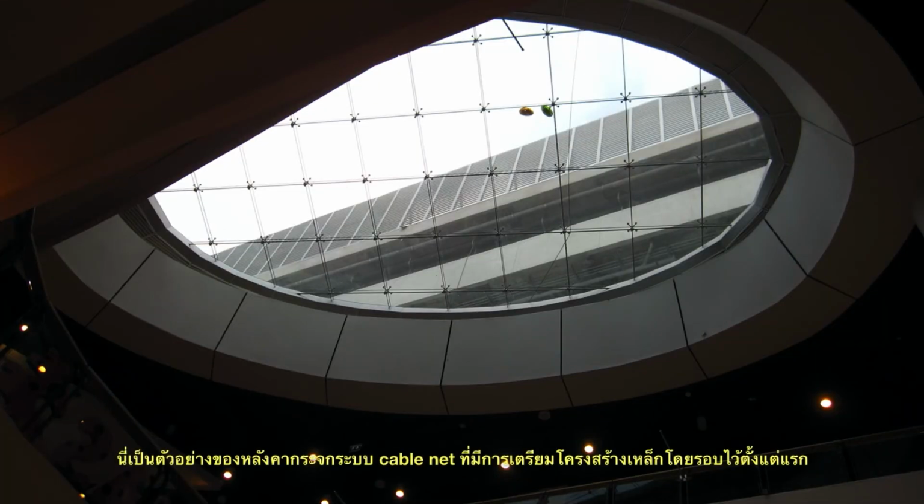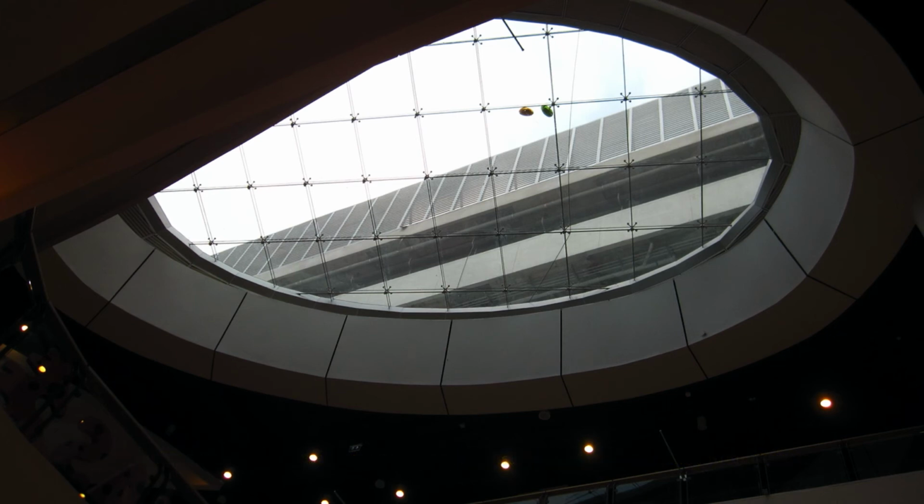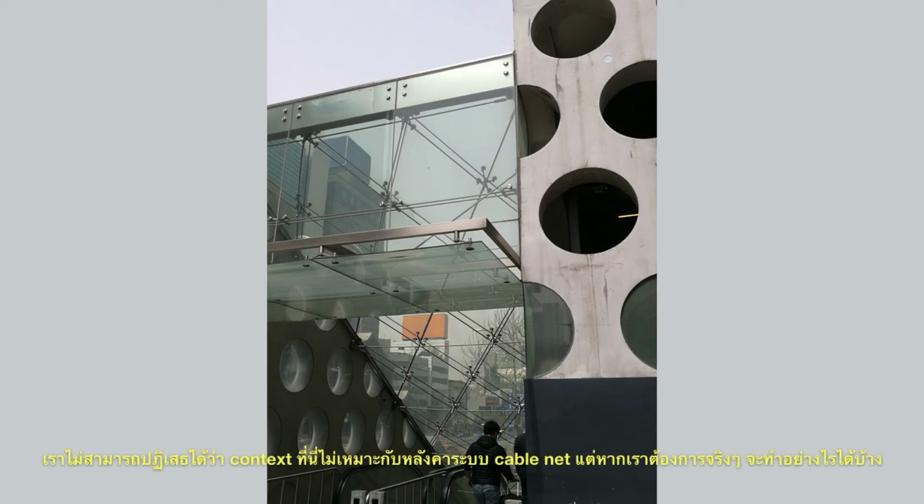This is an example of cable net skylight glazing that is done properly by having a sufficient boundary steel structure that was engineered for the tension forces since the beginning. We cannot deny the fact that the main structure is in a condition that is more suitable to take load vertically. But what if we really want to have a cable net system? What can we do?